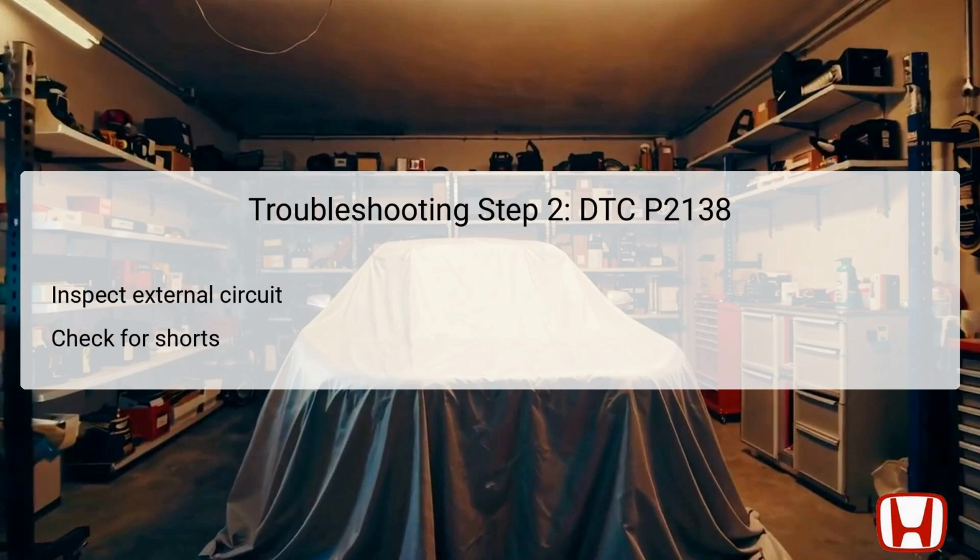Step 2 involves a thorough inspection of the external circuit associated with the APP sensors. Wiring issues, such as shorts, can significantly affect the voltage signals from the sensors to the PCM. Using diagnostic tools, the technician should check the APP sensor connections for integrity and continuity. If a shorted condition is found, it indicates that the wiring may be compromised or damaged. This inspection is crucial as unresolved wiring issues could lead to ongoing operational faults despite potentially replacing components that seem faulty.